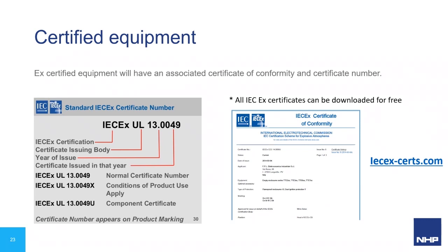Sometimes you'll find another letter at the end of the certificate number, either an X or a U, which indicates that there are specific conditions of use and that the equipment within this certification is a component only and must be used with other Ex equipment to be fully certified. The conditions are listed in the certificate and are like installation requirements, and you must follow these. So you would find this on, say, a push button or terminal designed for use within an Ex e enclosure.